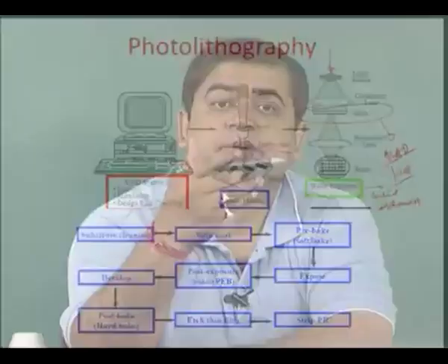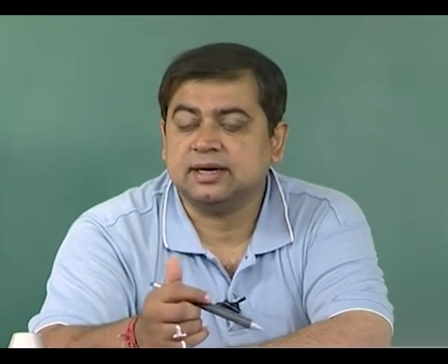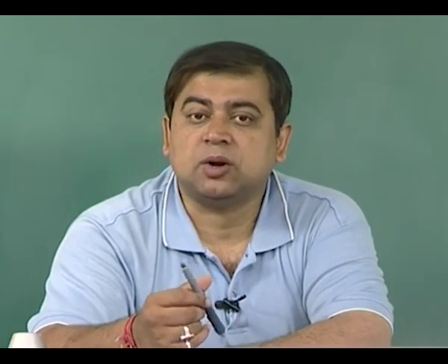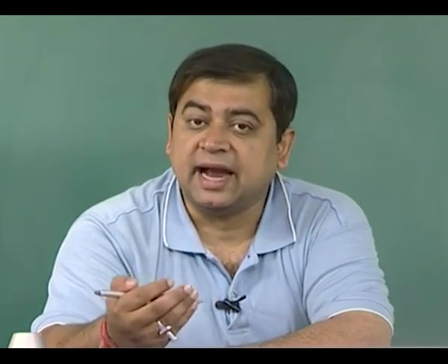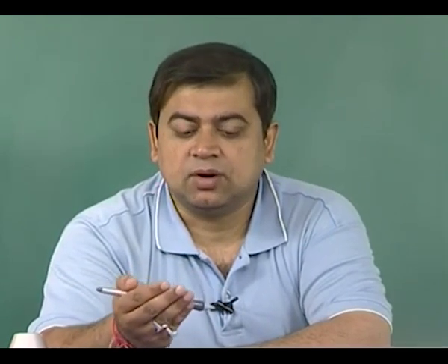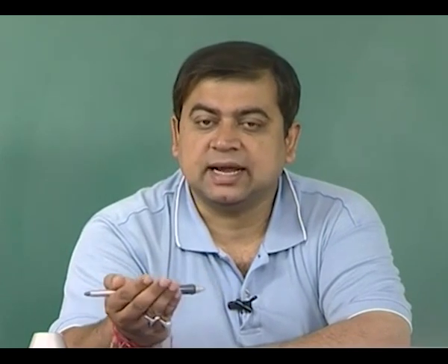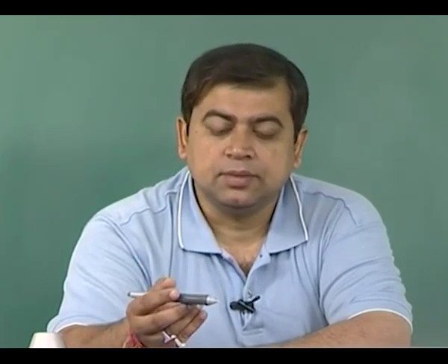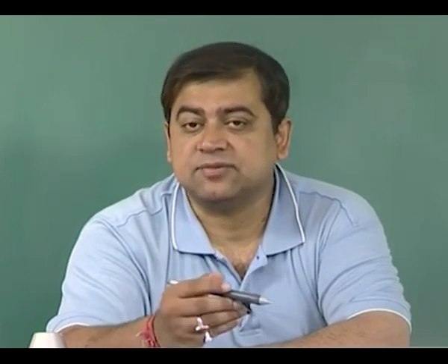You can get a printed transparency mask, where there is a Kodak Mylar film, which you can print at a high resolution of about 5000 dpi, dots per inch, using a photo plotter, and the power of CAD can again be used for printing different features and structures on this soft mask. And instead of using the hard mask, which is fabricated using a very complex e-beam scribing onto the surface, we use this soft mask, which can imprint or serve the same purpose.